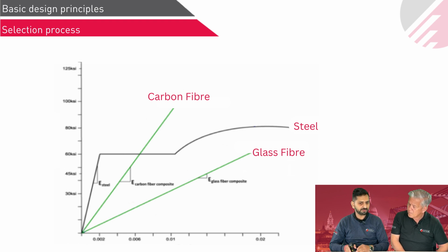So this is the major difference between steel and FRP design, because in steel we already have the yield stress, which could be 500 MPa, 400 MPa depending on grade of steel, whereas in carbon fiber we need to derive that tensile stress depending on the strain values and all those things.